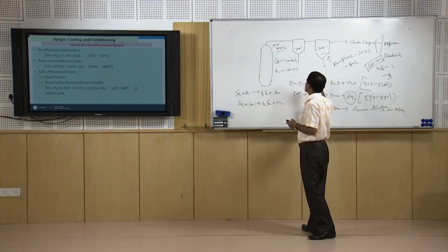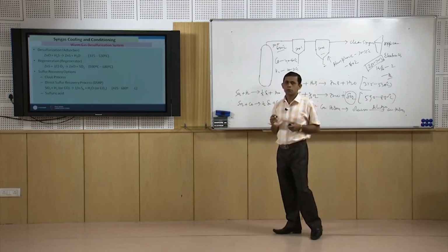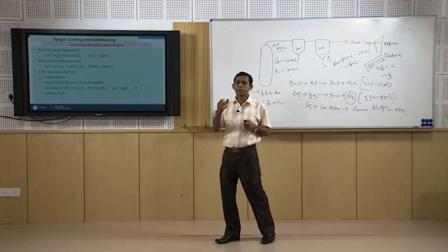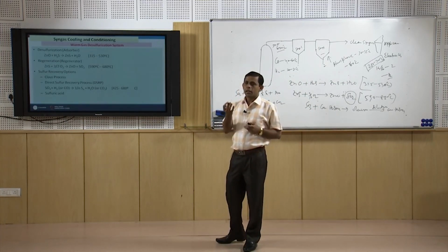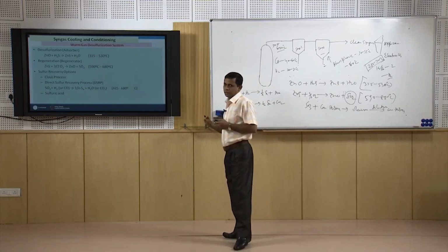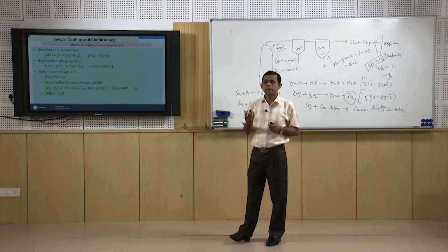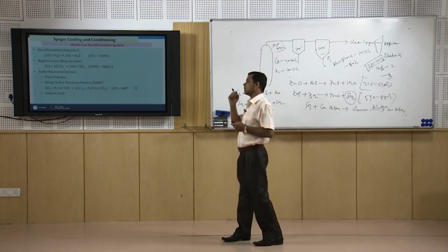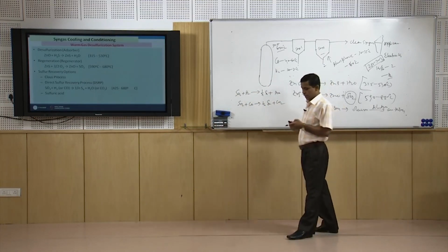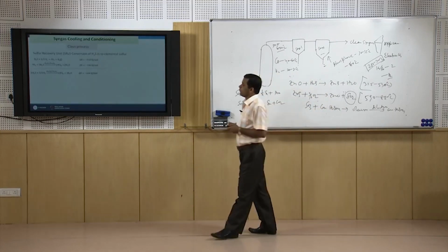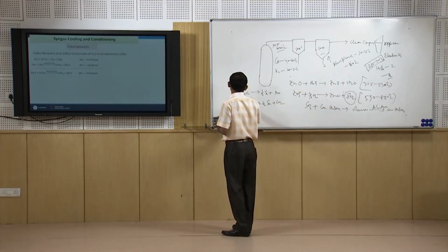For the solvent absorption method also, using Rectisol, Selexol or MDEA, when it is regenerated, or desorption proceeds, the H2S comes out. So, that H2S can further be used for sulfur recovery through the Claus process. Now, we will see the reactions involved in the Claus process.